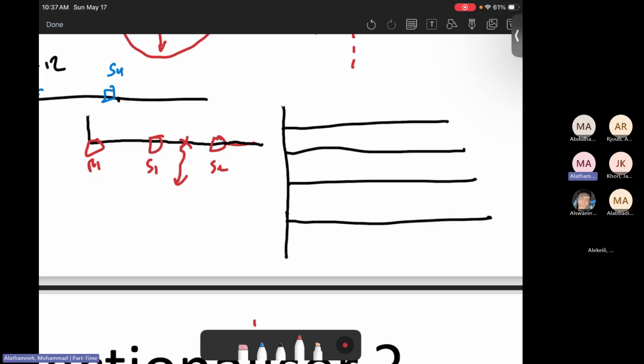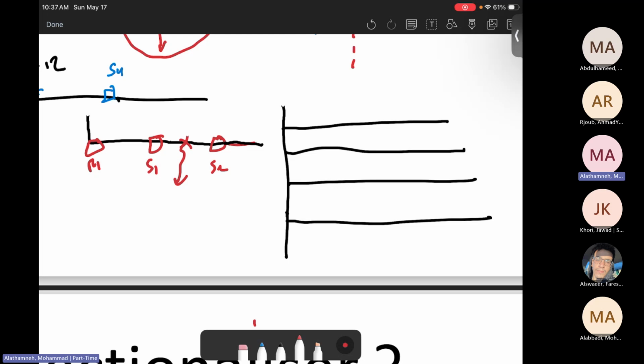The faults happened here. Here is R1, here is S1, here is S2. So in R1, it used to be on until reaching the faults, then it will be off. After that, it will be on for a short period of time, then back off. After that, the fault continues, then back off. So here is the first trip, the second trip.